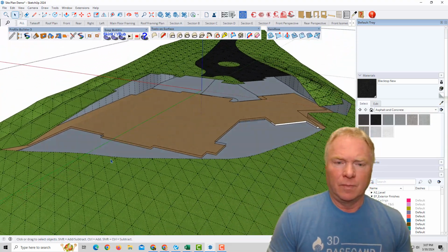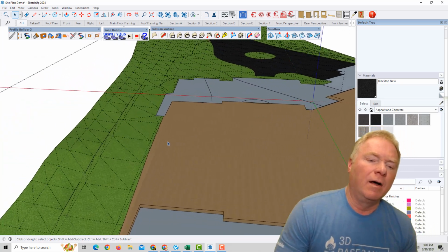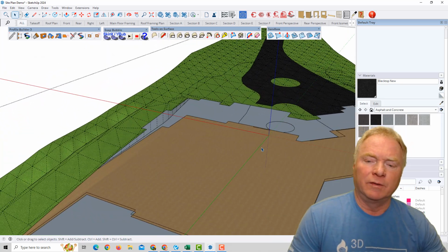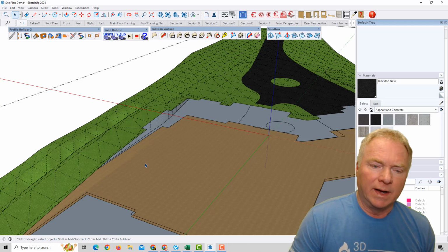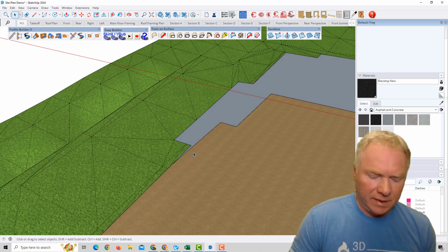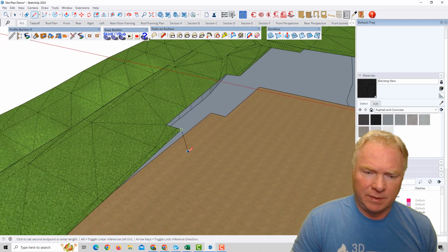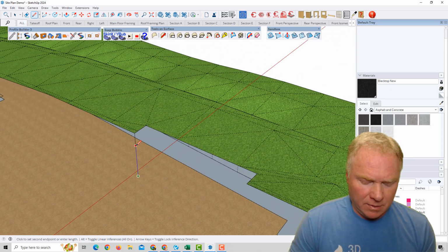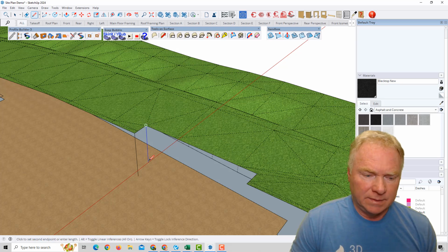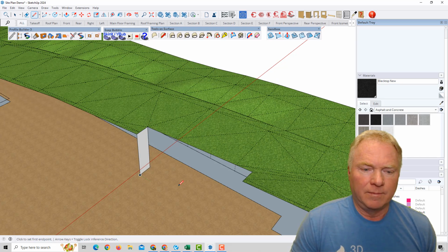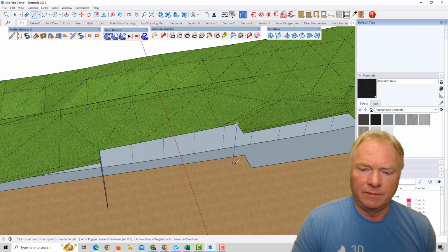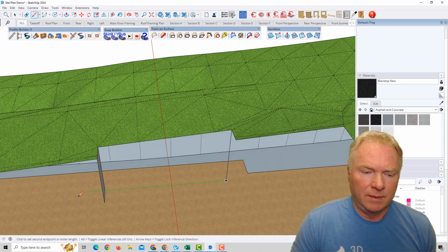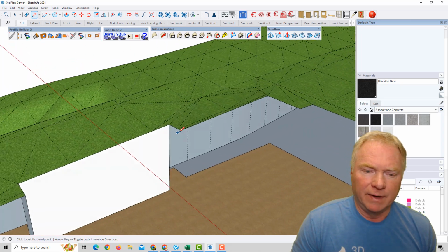Okay, that makes sense. Now around the house, in the other videos you saw how we did that moat all the way around it. I'm going to basically get rid of the rest of that subgrade by doing the same as we did in the second video, because I'm just going to go around my backfill lines and get this down to this new part where we're backfilling it, right?